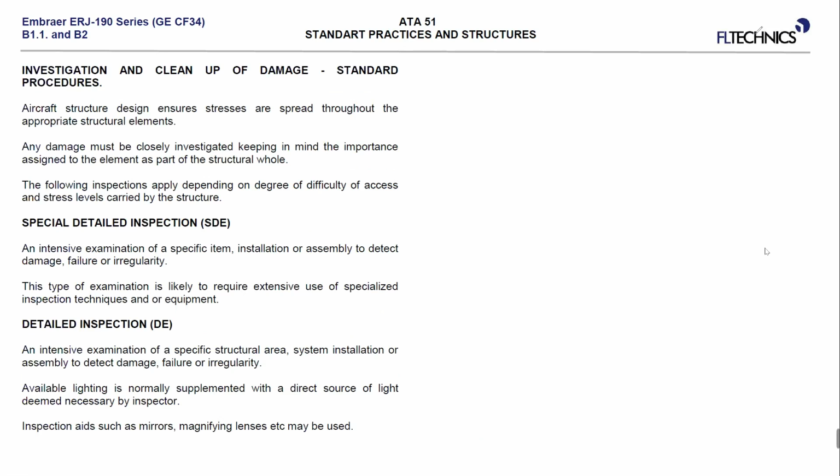And the guys who were responsible for this aircraft to investigate and evaluate the damage, they found nothing in the SRM, which is a restriction for dents on the stringer and on the frames. Okay, there were no holes, just dents. So they found nothing in the SRM, and they said, okay, if there is nothing in the SRM, we can release it.